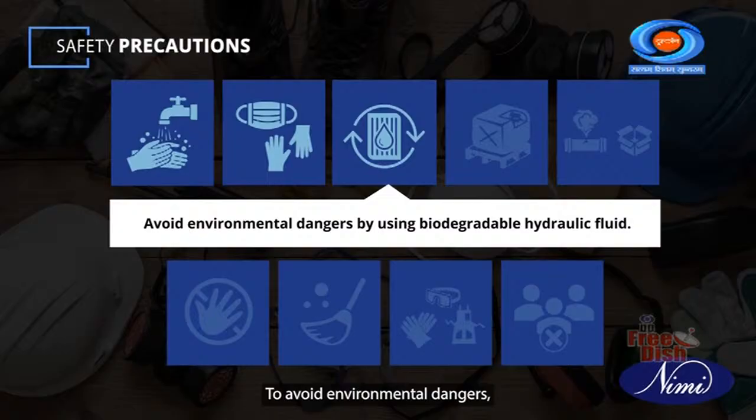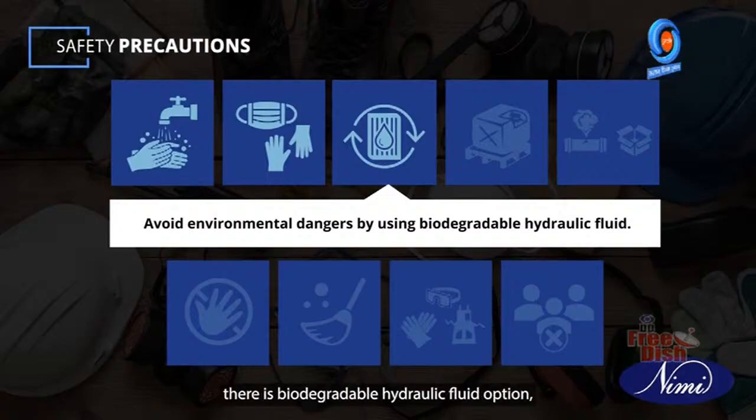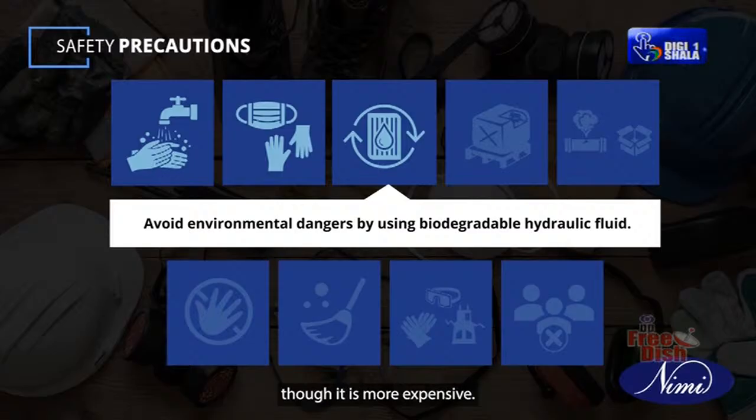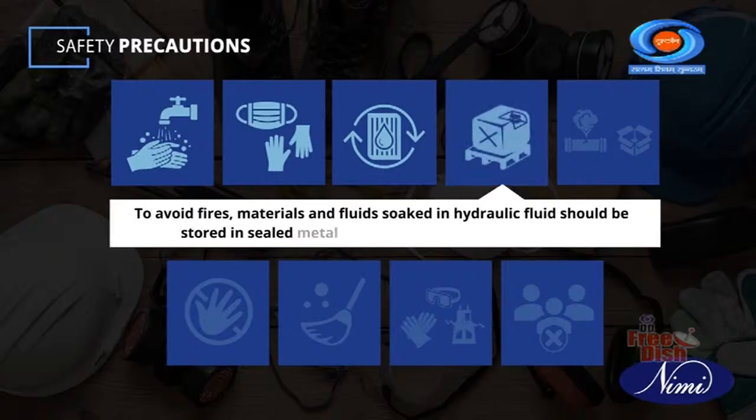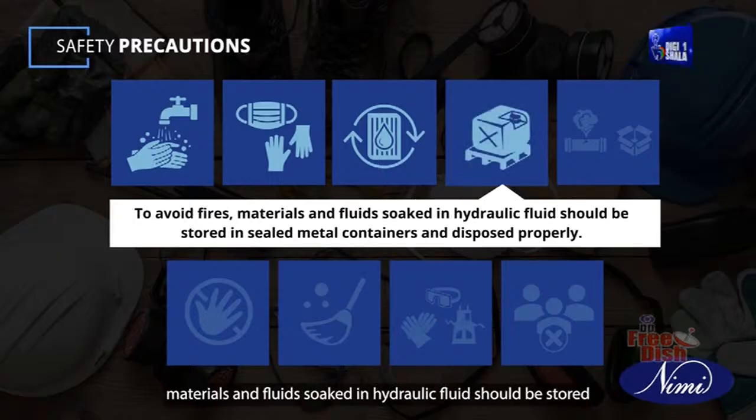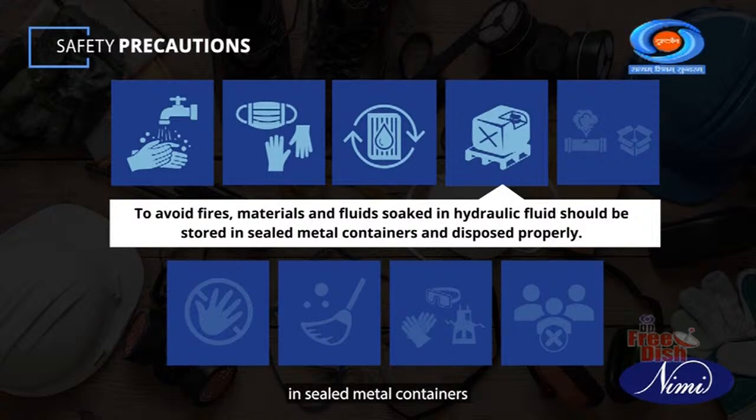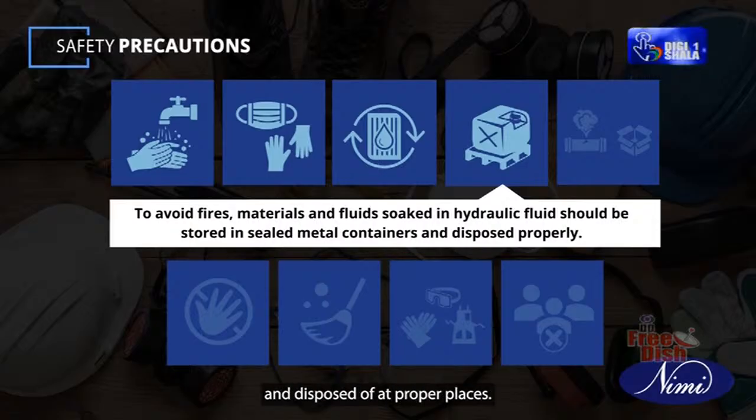To avoid environmental dangers, there is a biodegradable hydraulic fluid option, though it is more expensive. To avoid fires, materials and fluids soaked in hydraulic fluid should be stored in sealed metal containers and disposed of at proper places.